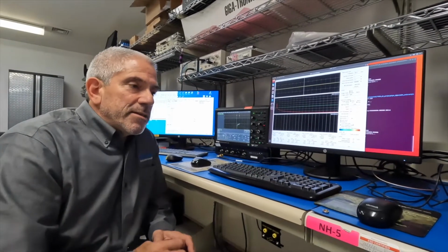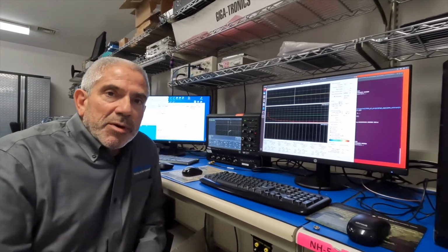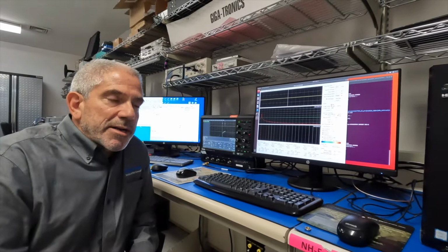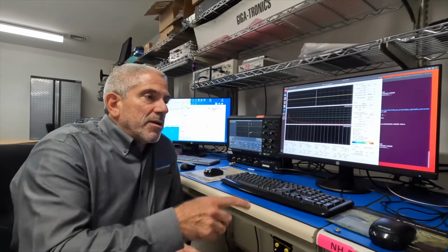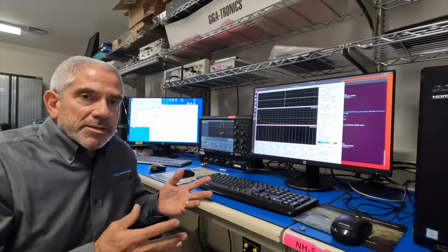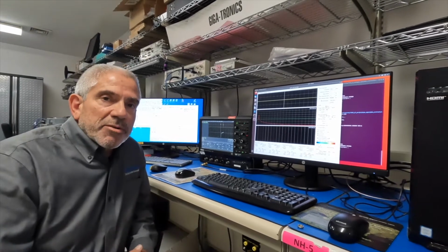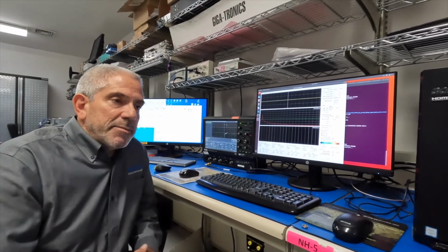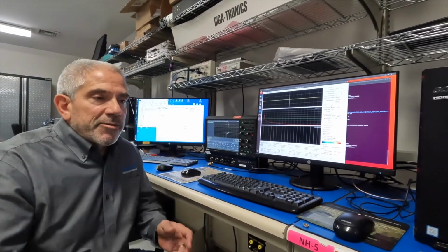So what we're going to show you today, the specific feature, is pulse descriptor word extraction from received pulse parameters, or RPP-PDW extraction. And what we use to generate that is an RF SoC, an RF system on a chip card in one of our computers. It's going to be taking in RF and sensing it. It's going to be doing digital signal processing, and spitting out in real time all of the received pulse parameters that it sees, and putting them into what are typically known as pulse descriptor words. So pulse width, PRI, center frequency, etc. And we'll show you how some of that works today.